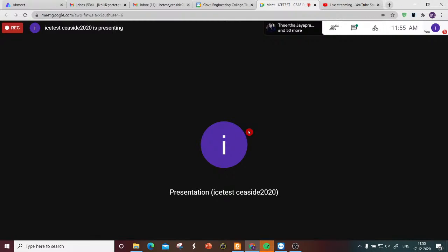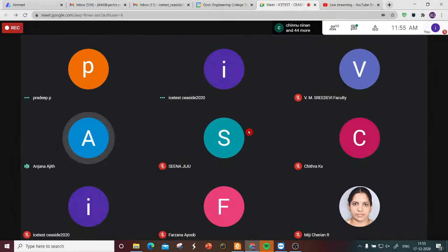How will you get this sintered fly ash aggregate? I obtained it from Jindal Power Corporation. It is in powdered form. It is pelletized, then fed into rotary kilns and heated up to 1200 degrees centigrade, where it forms into a round ceramic aggregate form, porous form.